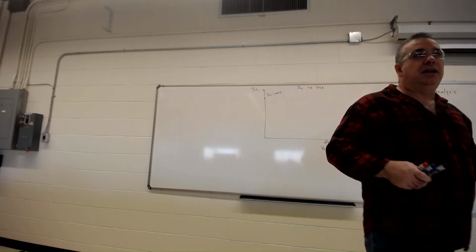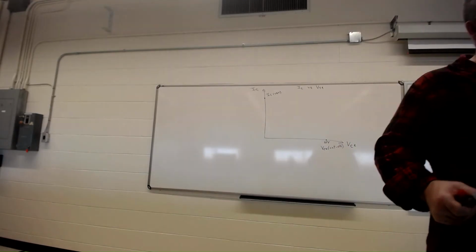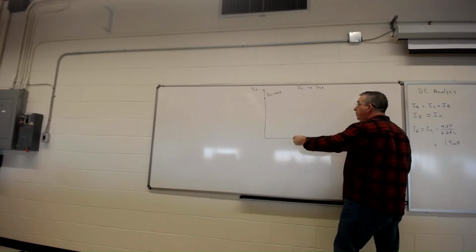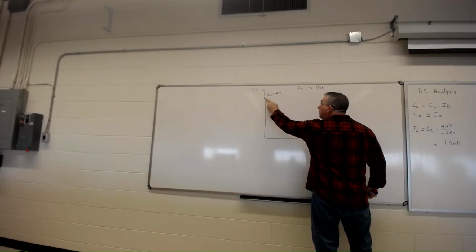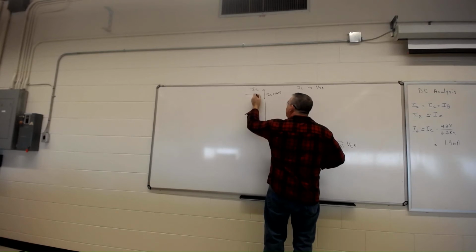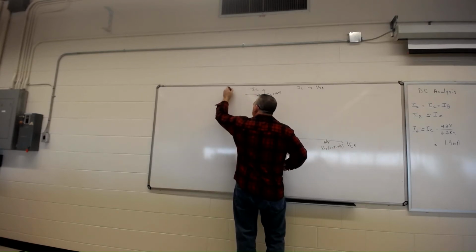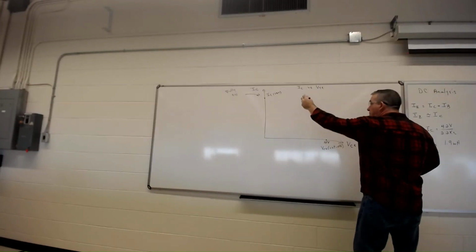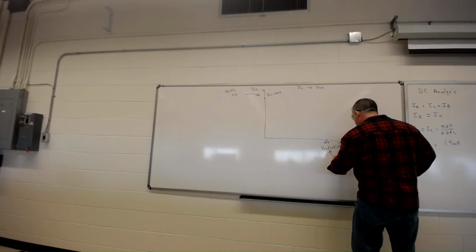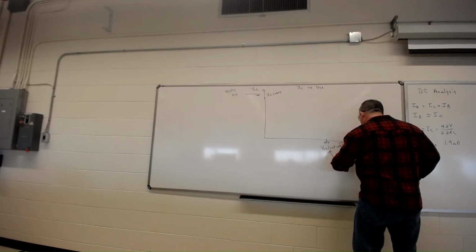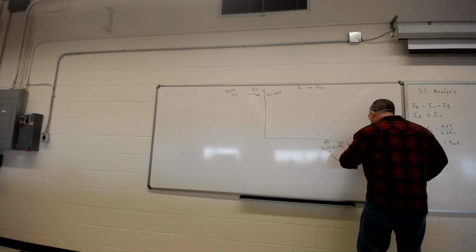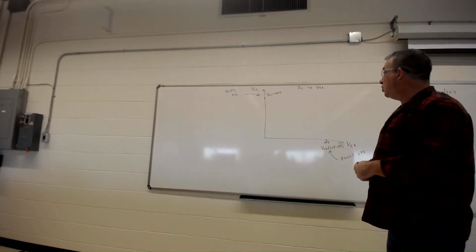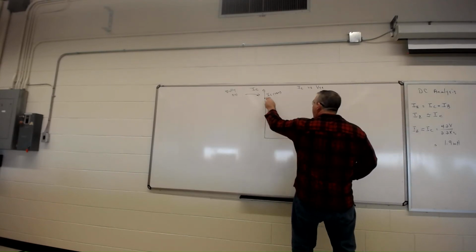If the transistor in this circuit was being operated as a switch, as we first saw, the transistor would either be here, fully on, so this point means fully on, as much current as you could run through it, or it would be fully off, with no current going through and all the voltage falling from collector to emitter. So if it was a switch, it would be either here or here.